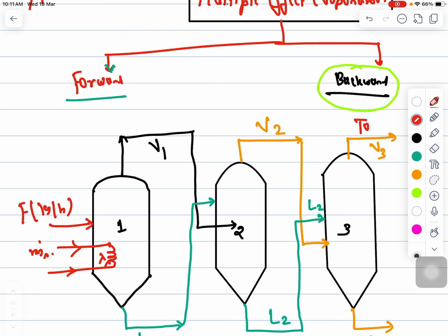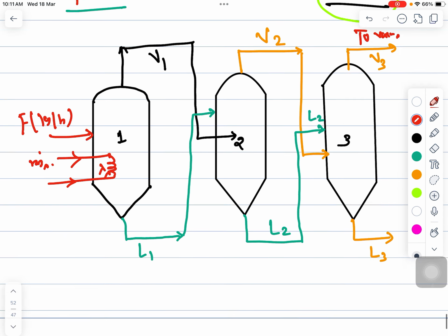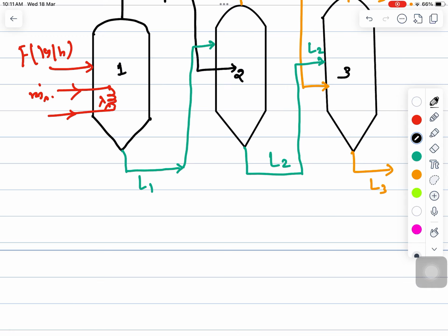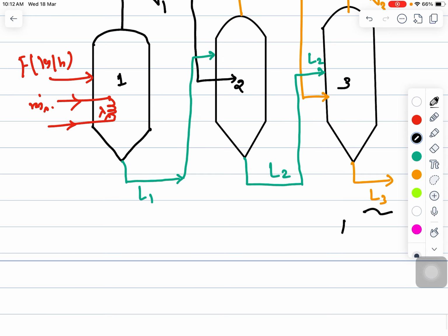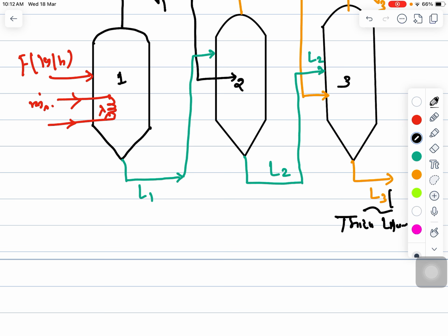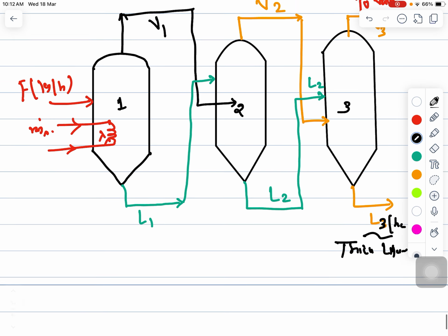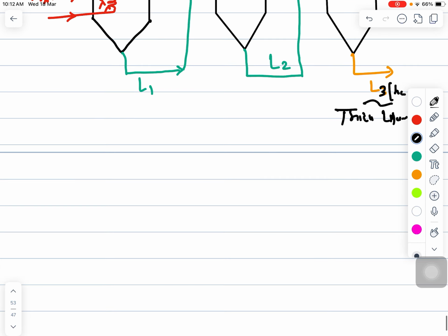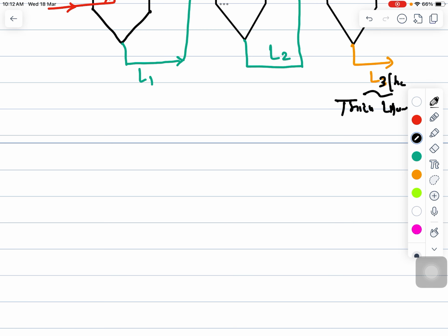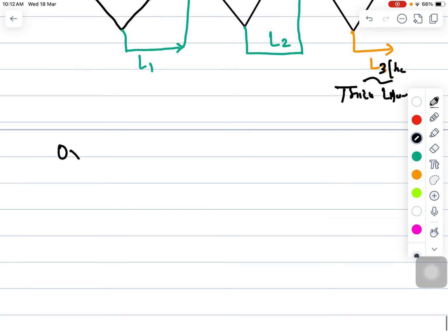Sometimes it is connected to the vacuum system. So basically what is happening here, in the evaporator we are removing the moisture content of water. So at the ultimate end, you will see there is a thick liquid product, having a unit in kg per hour or something like that. Okay, so there are three effects, and we have seen there is input, there is output in all these three effects. So first I'll perform the overall material balance for a triple effect evaporator.